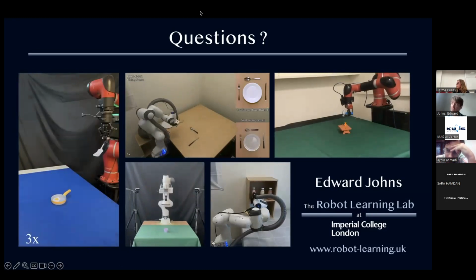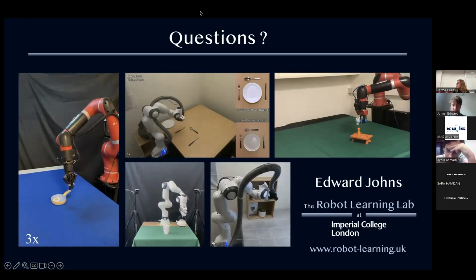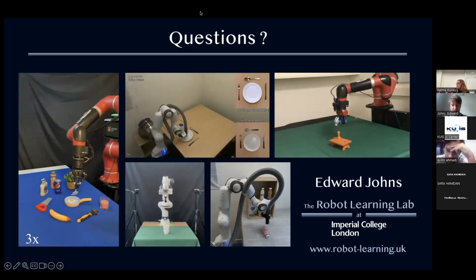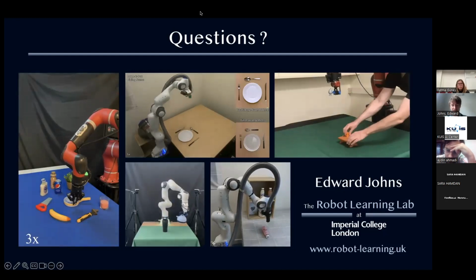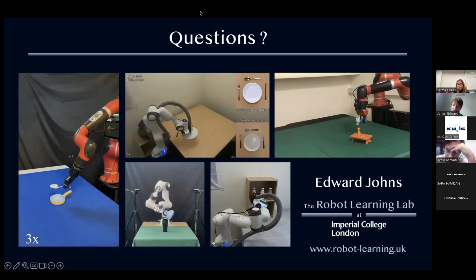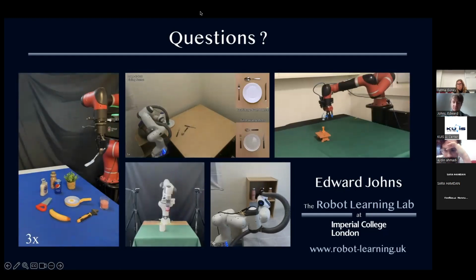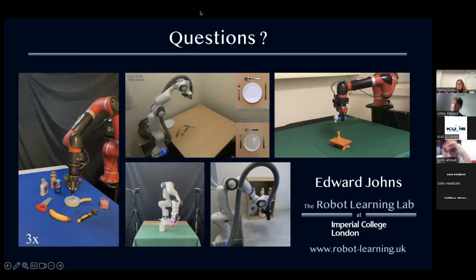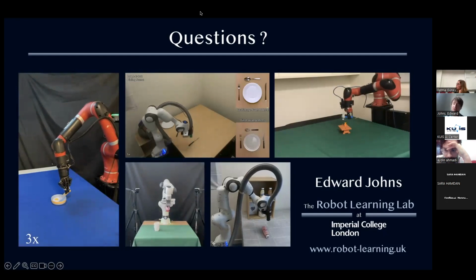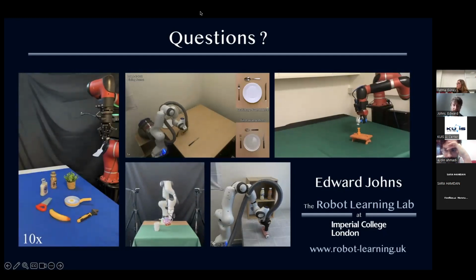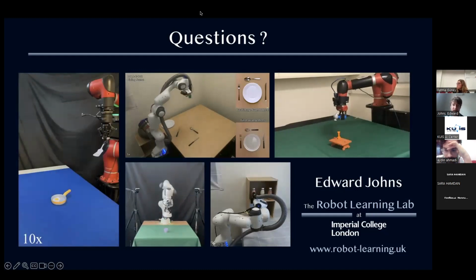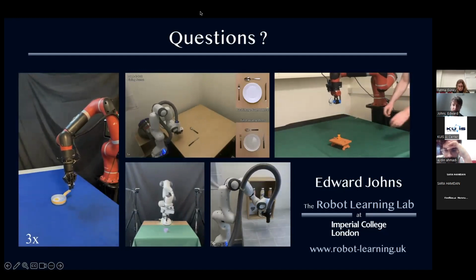There are a couple of things that we do in our imitation learning work. One of the inductive biases is that we treat object manipulation as a pose estimation problem, where we try to predict the pose of where the object is and then move the gripper to that object pose. A lot of our work is about saying, where is the object in the environment? And then once I know where it is, the robot can then move to that pose,